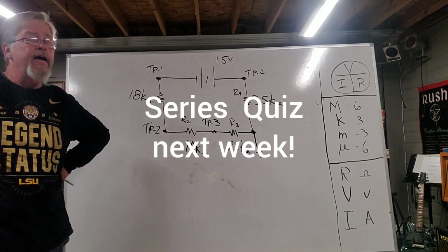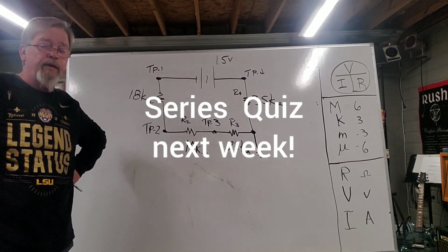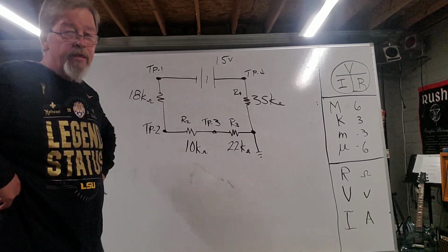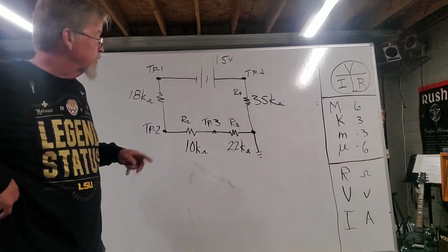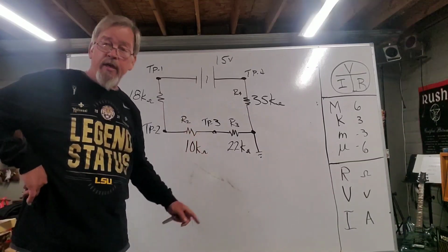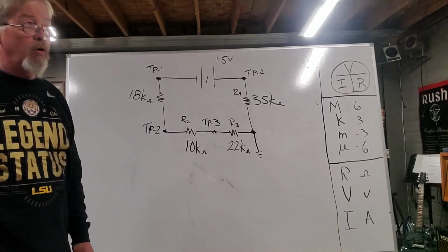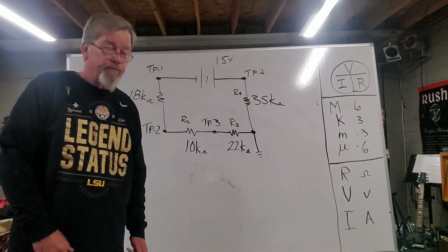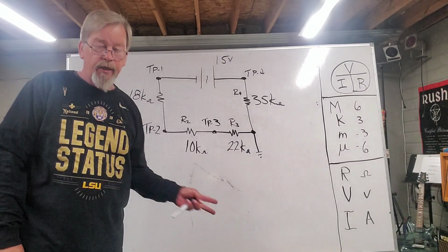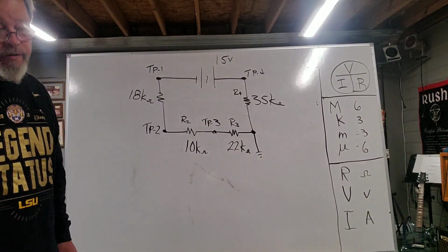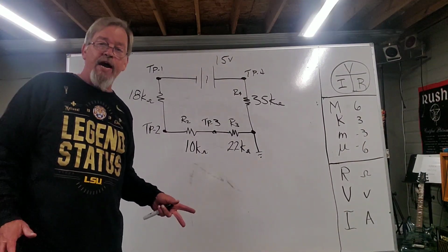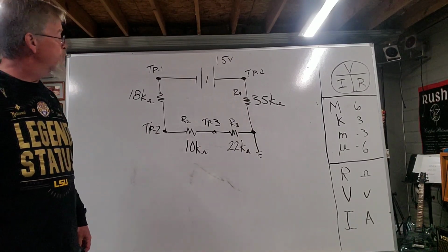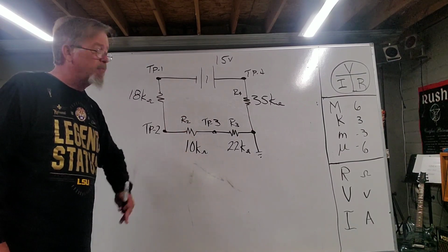I'm thinking we're going to need to have a quiz next week, get this series circuit. The quiz is going to simply consist of one series analysis problem with test points. So, study all that up. Make sure you remember the common points within the series circuit. Current's the same, you add up resistors, and the voltage divides and adds back up to the total voltage. Okay, so there's number 3.